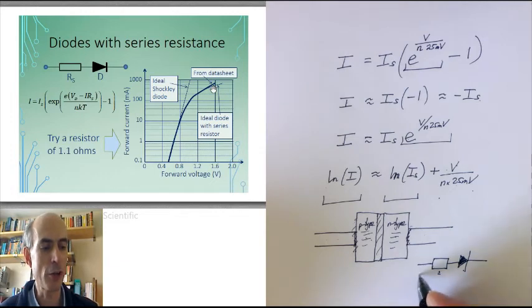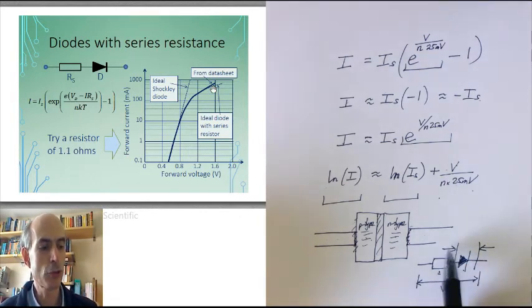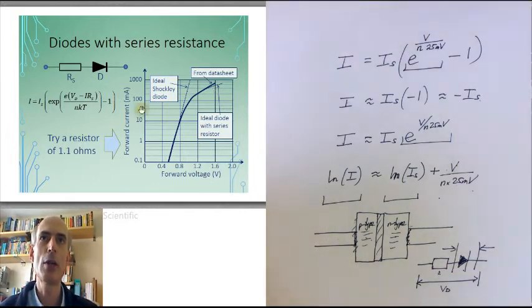the entire diode, that's this, and calling that VD, and then determining that the voltage that we have to use in Shockley's equation, that's the voltage across the diode component only, is VD minus the voltage across the resistor. And the voltage across the resistor is the current through the resistor times the value of the resistor. And we'd end up with this equation here. It's not a particularly pleasant one to try and solve circuits with, but we'll be looking at techniques for how to do that a bit later on.